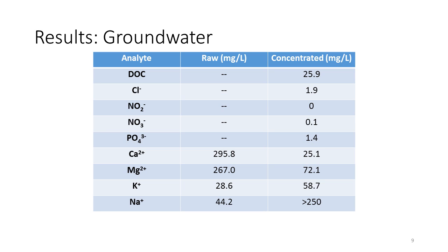I'm not sure if that was very well defined. So usually when we say recovery, that's what you mean. So does 10% of the feed flow go through the permeate? That's the recovery of that specific element. So I was just curious where it lies in the realm in which these things operate. So, in the membrane? Dow NF270? Say that again? NF270 is a softening membrane. It's probably tighter than that.